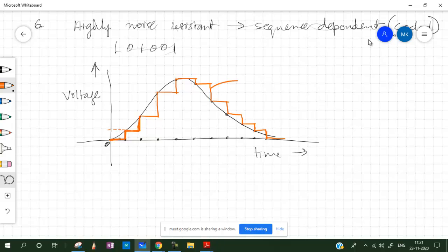All right, so this is the digital, or you can say digitized signal, and this black obviously represents the analog part of it. If you see it in different ways, it is able to reconstruct a similar pattern, but what is happening is it's actually losing some of the values in between the sample points. So that's how you go into the analog to digital conversion and digital to analog conversion. This is how you basically construct it.